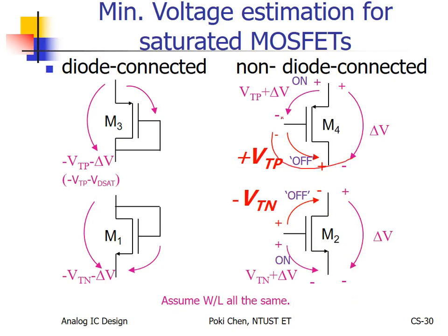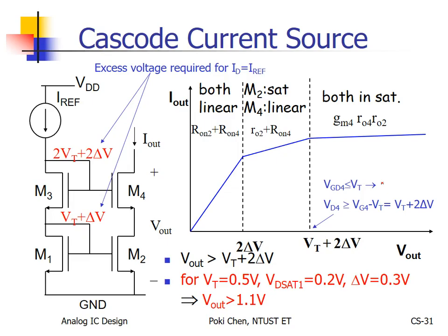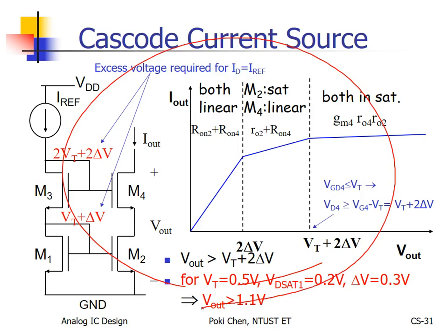And again, how about PMOS? The drain can be 1 VTH higher than the gate. Please keep this in mind, that is very important. For NMOS, the drain can be 1 VTH lower than the gate, down to your ground. For PMOS, the drain can be 1 VTH higher, back to your VDD. Both can expand your output swing. I think I taught this already, right?